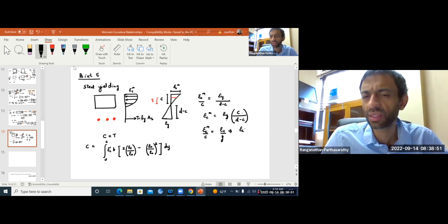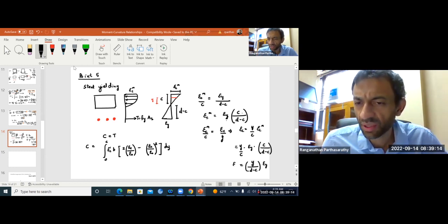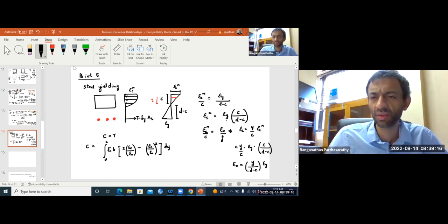So your epsilon C is just y over C times epsilon CM, so y over C times epsilon Y times C by D minus C. That becomes y by D minus C times epsilon Y. So that's your epsilon C, and we have epsilon C in terms of y.